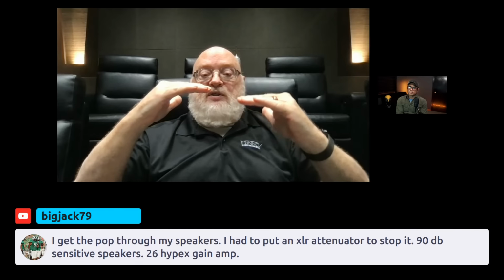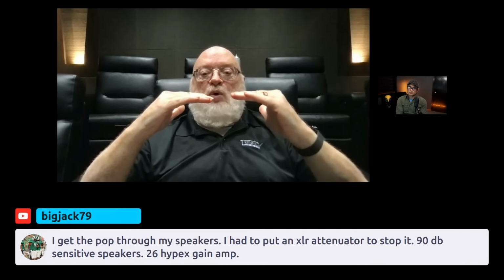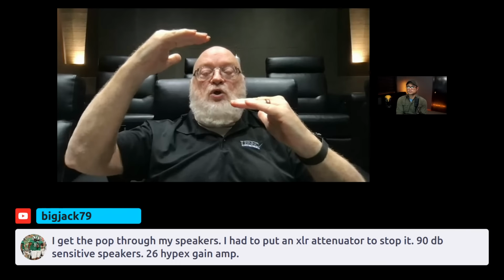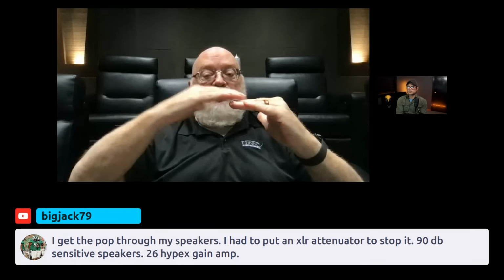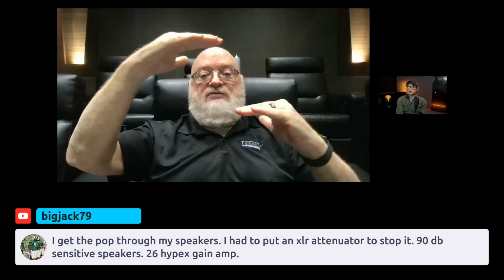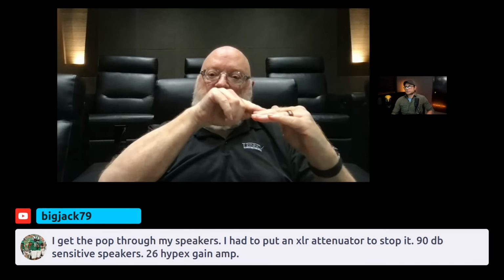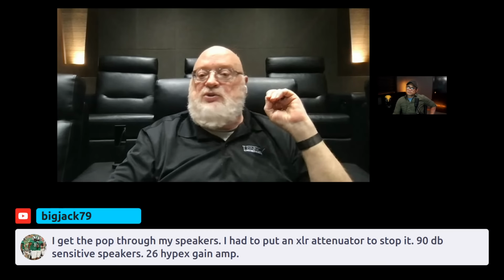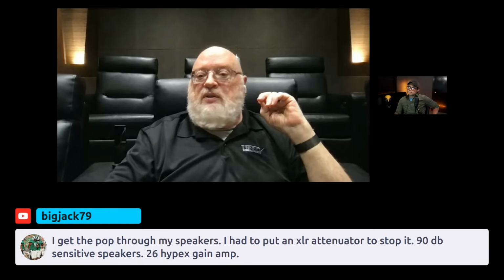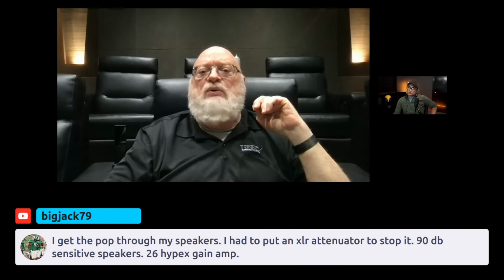Ideally, you'd want those things to run out of gas at the same time. Because if one starts clipping here and the other could have gone all the way up here before it starts to clip, all of this space in between, if that's a 10 dB difference, that's 10 dB of signal that you really can't access because this is already sounding terrible. And that means you lose 10 dB of signal-to-noise ratio. It's basic gain structure. It's really well understood in the pro business, and for some reason the consumer business has never really figured it out.